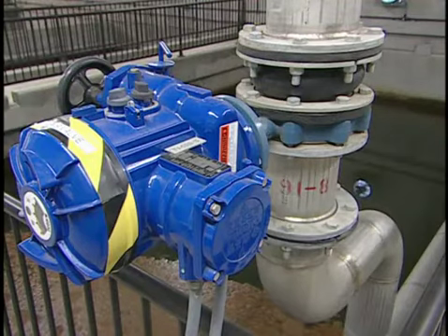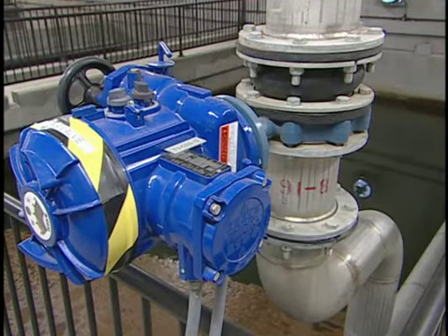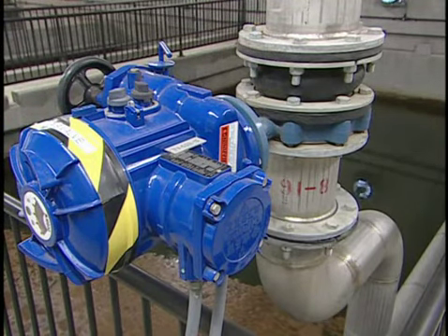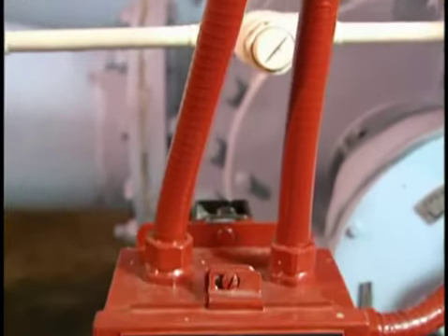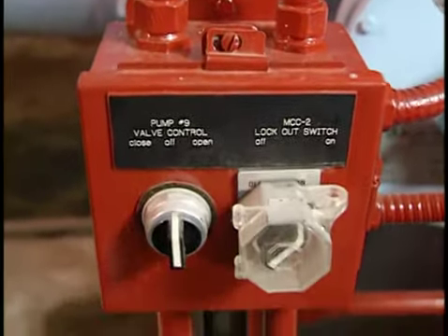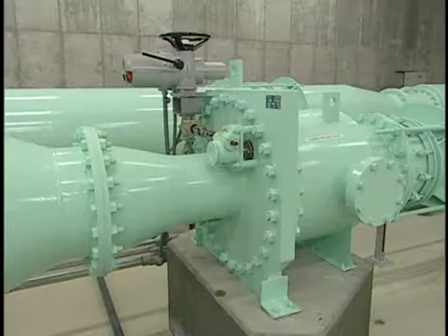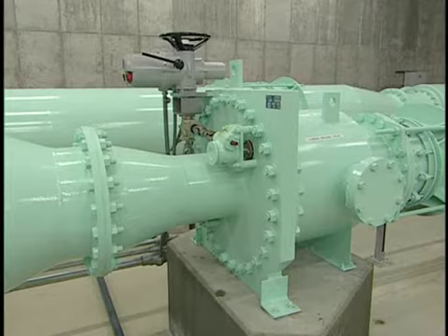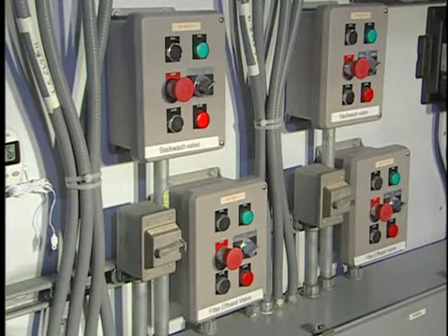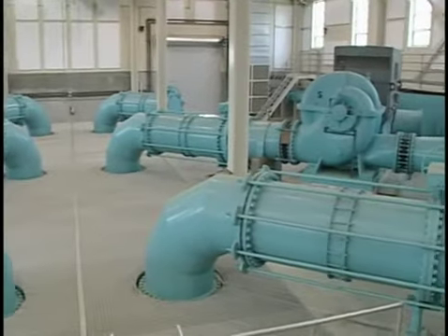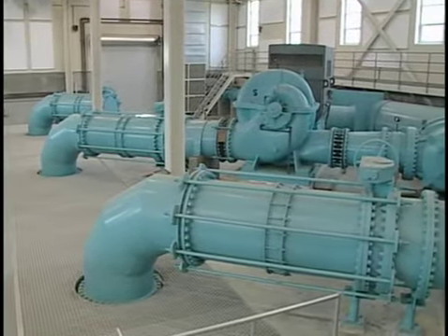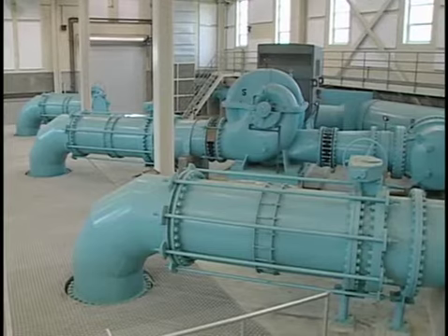An electric valve operator uses a small motor to rotate the valve stem through a gearbox. The motor is activated by a switch and is turned off by a limit switch when the valve is fully open or closed. Electric units can be set to intermediate positions for throttling flow. The disadvantage of electric units is that if there is a loss of power, either standby electric service or manual operating handwheels are necessary to continue using them.